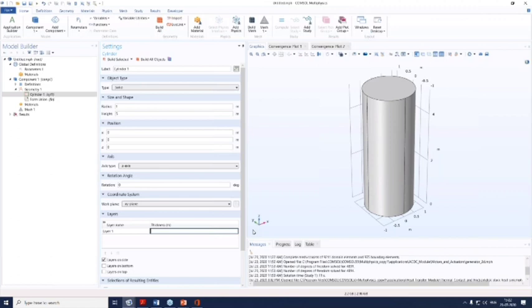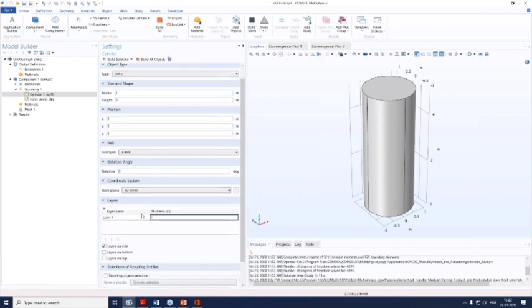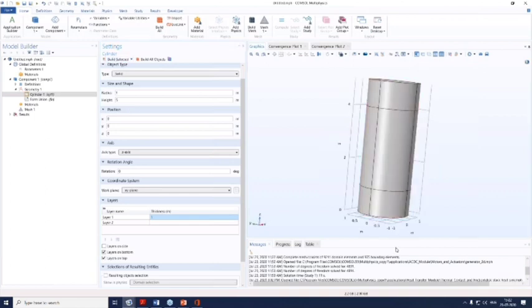let's say, 1. And here I can say whether I want to have layers on the sides or top and bottom. I'm just creating layers on top and bottom. You will see that this is how the structure is getting divided. So this is also one of the ways you can partition your geometry. Again, as one of you is asking how to model the internal structure of the capacitor, it will all depend upon what kind of geometry or design you have in hand.